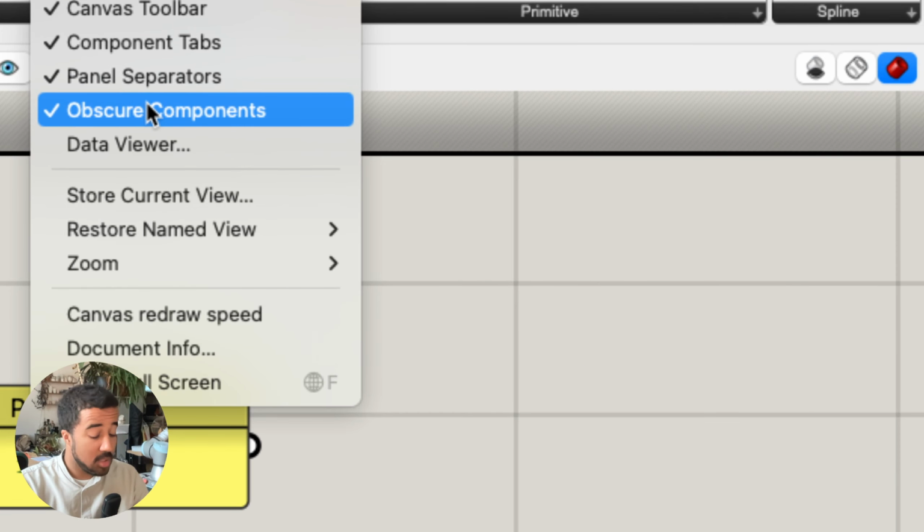There are different ways of previewing the geometry that we create in Grasshopper in Rhino. To demonstrate this, I will simply add a sphere component, and you can find this under the Surface tab, and under the Primitive section there will be a sphere component that we will place on our canvas. I will simply use this panel with the value 100 as my radius, and there you can see we created this sphere that is previewed in red.